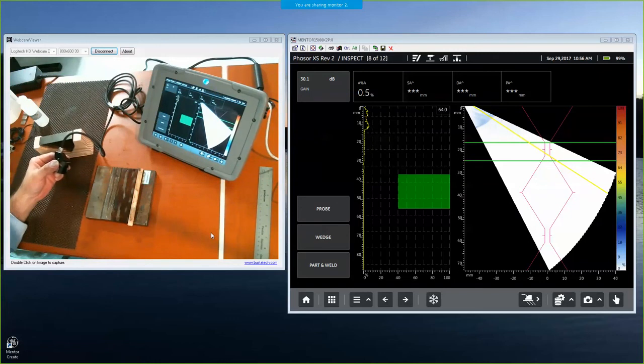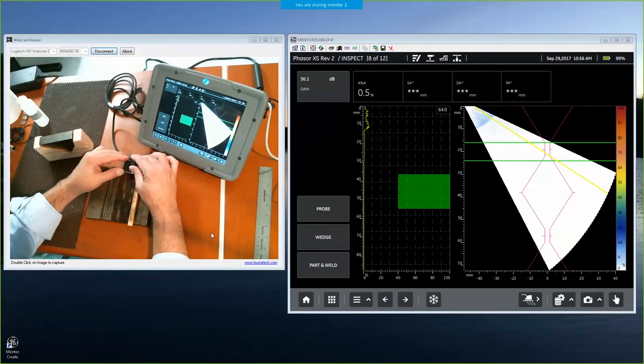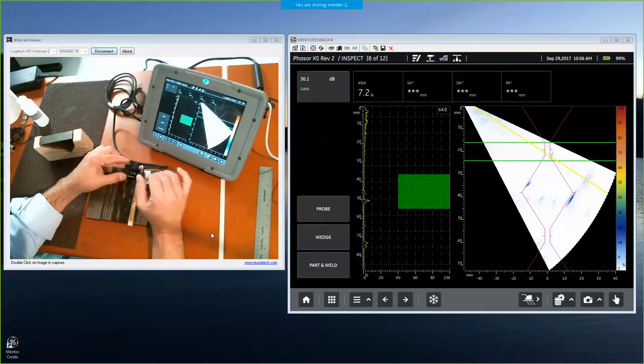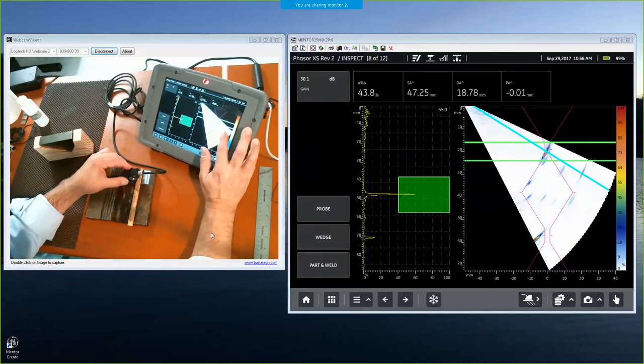Okay. So should we move ahead? Yep, let's keep going. All right, so I just skipped to the next panel, which is we've done all of our calibrations, and we're just going to do some quick hand scanning. So I've got a sector and an A scan. So scan along. Oh, there's something interesting. I've already got the selected beam up there. But yes, I can select our beam.